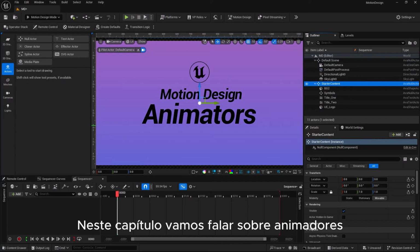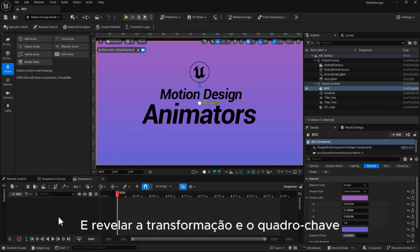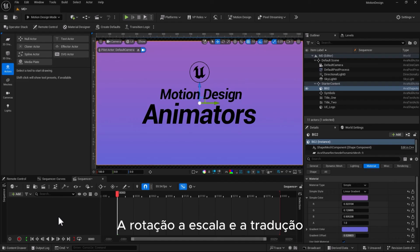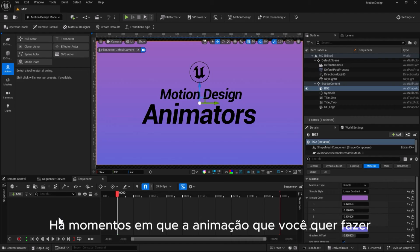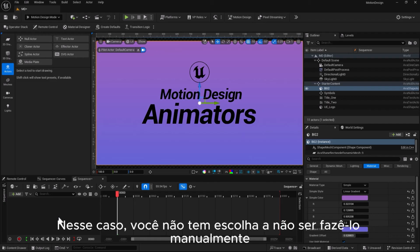In this chapter, we are going to talk about animators. Instead of the laborious task of bringing every single element into the sequencer and revealing the transform and keyframing the rotation, the scale, and the translation, we can leave that to the animators in the motion design tool, and it's going to do some automated preset type of animation for us with a good degree of control. Obviously, there are times where the animation you want to do cannot be found in the animators dropdown. In that case, you have no choice but to do it manually.